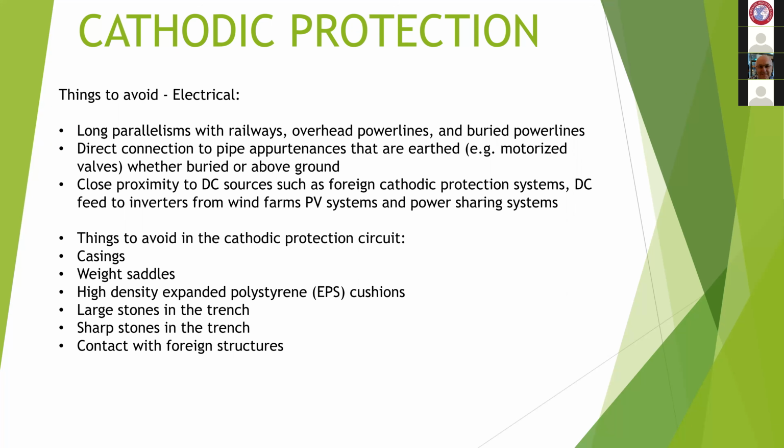Avoid any direct connections with anything on the pipe that's connected directly to earth, because as we mentioned earlier, the very low resistance of the earth will take a lot of the current away that you need for your cathodic protection.